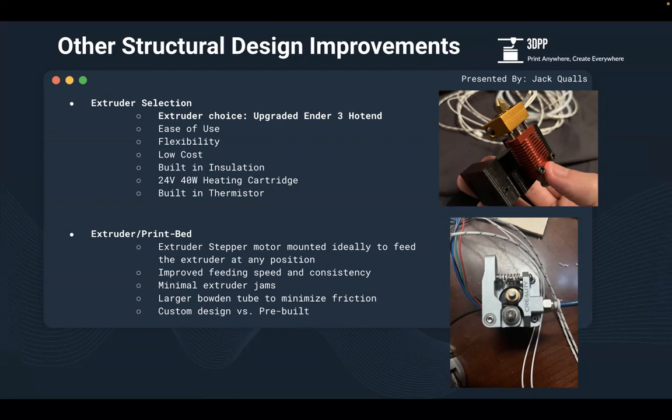As for the print bed, as we mentioned before, we forwent the heated print bed and instead wrapped it in duct tape, which we researched and found was a pretty easy solution to improve your bed adhesion without needing to heat the print bed, which saved us a lot of energy from needing to constantly heat that.